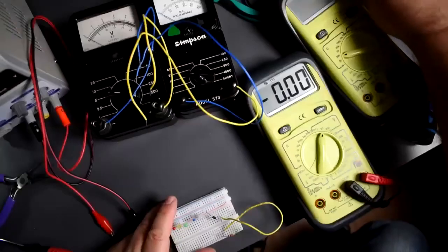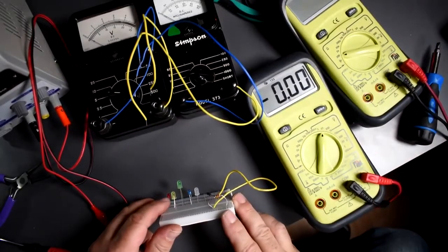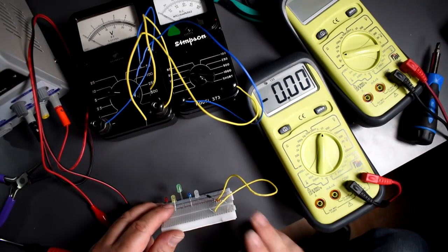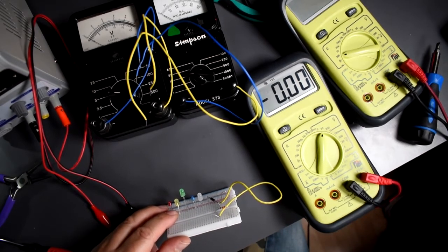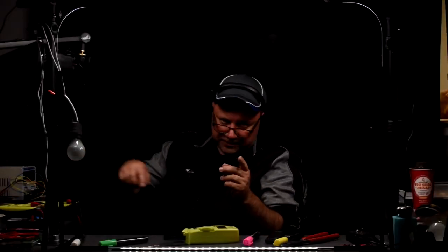So I have put few LEDs together, different colors, and we're going to take a look. We're going to measure the forward bias voltage. The forward bias voltage is the voltage that is going to cause a minimum current to light the LED up. And once that forward bias voltage reaches its nominal point, it's going to stay there. That's how the diode works. Forward bias voltage, once it gets into a diode, it stays there. The voltage across the other components that are in series might change if you regulate the whole power supply, but the voltage across the diode is going to stay.